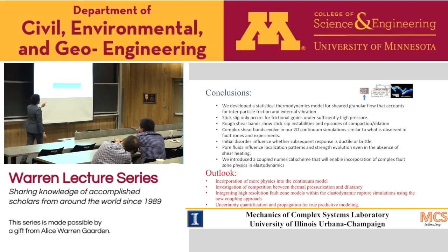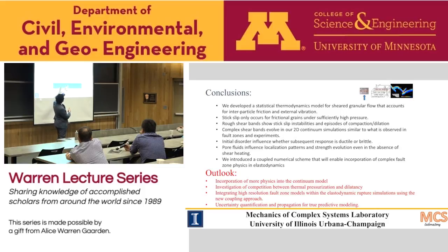So how we come up with this gradient term is that in the thermodynamic representation, we assume that there's also a flux for energy associated with the configurational degrees of freedom, and then the flux has to be the gradient of the potential. This leaves us with a tensor that we don't know yet. So it cannot be constrained by thermodynamics, except that it has to be positive. Since this tensor has the units of meters squared per second, we think that the fundamental length scale in our problem is the grain size.